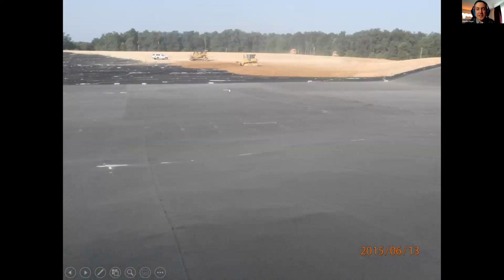You can see, just stepping further back, what this looks like. This particular part of the construction was when we were deploying soil over the interim cover. The interim cover is visible here in the foreground. You can see it has that very irregular shape. The final shape of the site was a more regular hill that had very straight slopes, anywhere from 4 to 5%, depending where you are.